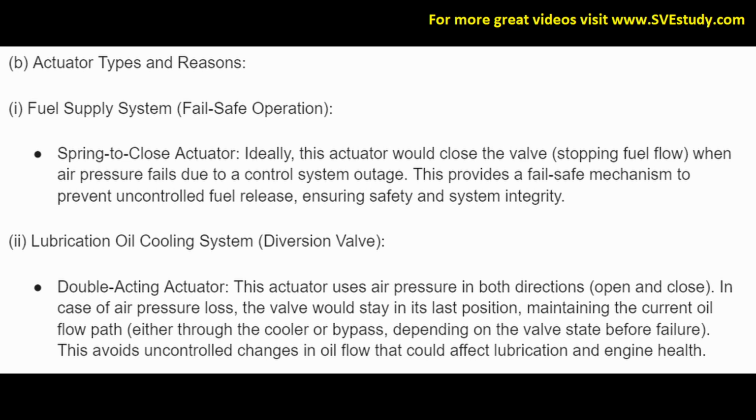Spring to close actuator. Ideally, this actuator would close the valve, stopping the fuel flow, when air pressure fails due to a control system outage. This provides a fail-safe mechanism to prevent uncontrolled fuel release, ensuring safety and system integrity.